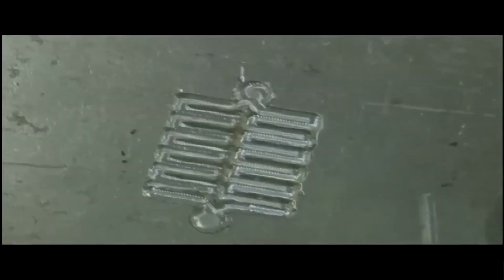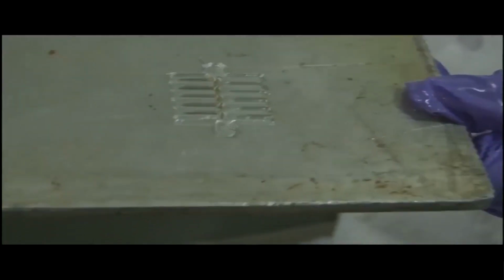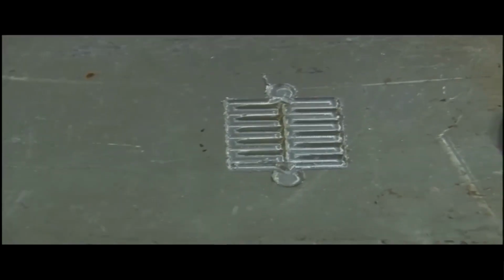This is a serpentine movement, and these are straight movements. We did not do finishing. This is just a rough machining cut that we have made using the end milling cutter only. We did not use the ball milling tool to finish it. This was just to show you how that happens. This is the laboratory demonstration on CNC 3 axis vertical milling, and CNC machines, as we all know, are capable of producing so many complex surfaces. That is also possible. This was a very simple profile that we picked to show you how CNC machining actually happens.